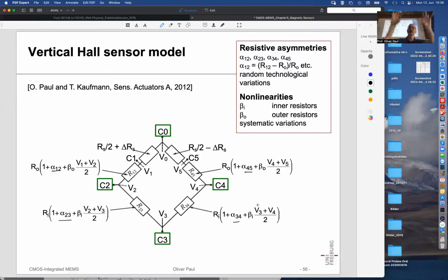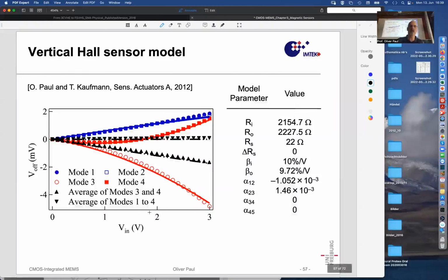So usually you have the resistances and then you just calculate your half bridges, your R divided by R1 plus R2 and so on, and then you have the voltages. And now the voltages depend on the driving condition because it's an intricate problem. But fortunately, you can disentangle this problem by doing some Taylor series expansion. I mean, these effects are small, and so you can do a Taylor expansion, and that ultimately enabled us to model that device realistically. And the outcome is shown here.